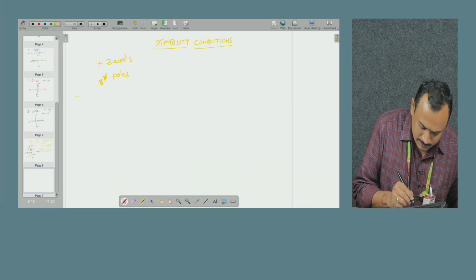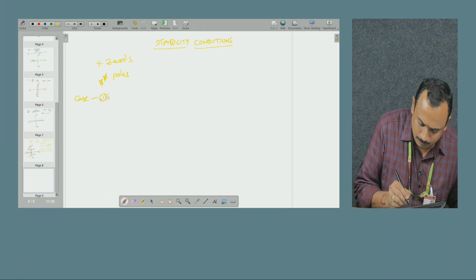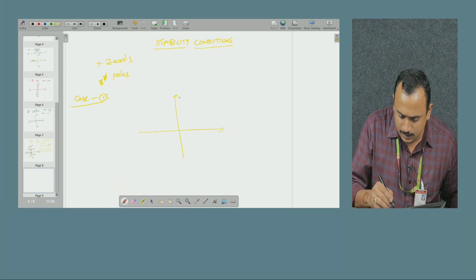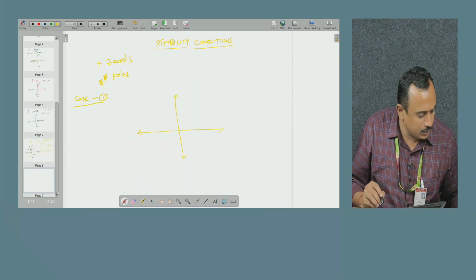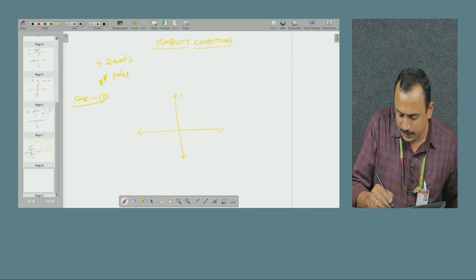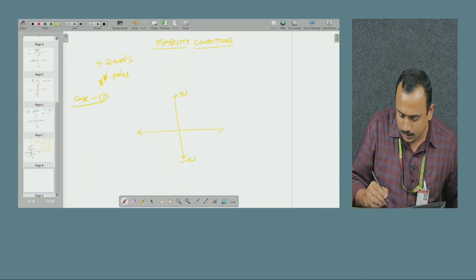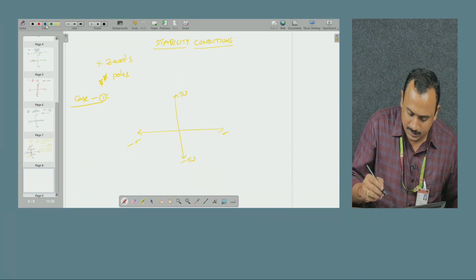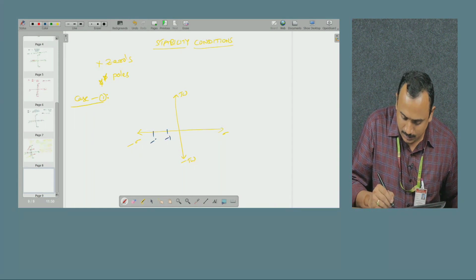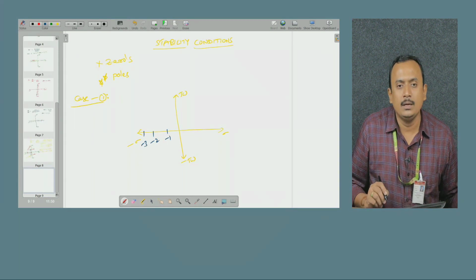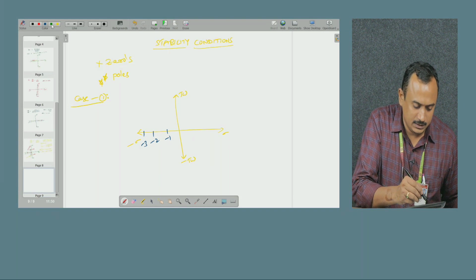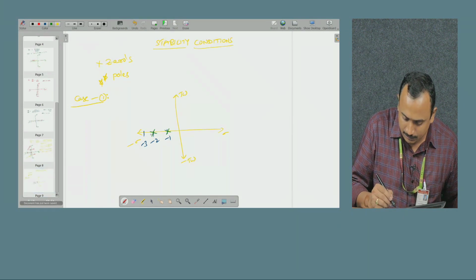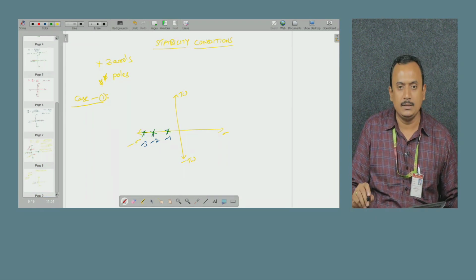In the first case, case 1, on the given S plane, if I find the poles only on the negative real axis, that is this side, left hand side, -1, -2, -3. For the given transfer function, let us say all the poles are lying on the left hand side of the S plane.